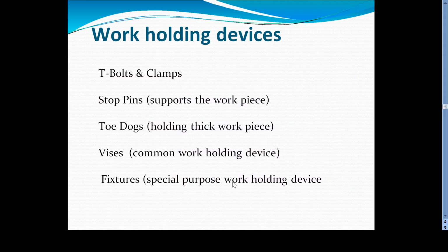Work holding devices commonly used in a planer machine are T-bolts and clamps, stop pins, toe dogs for holding thick workpieces, machine vices, and some special types of fixtures. This was already discussed while discussing the work holding devices of the shaper machine.